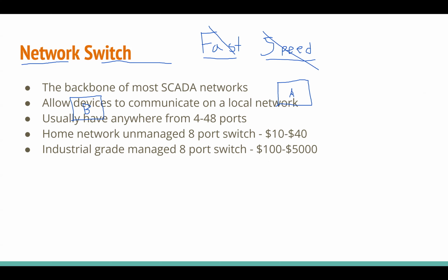It's reliability mostly. That's the really big one. I've already mentioned that we want to use SCADA now to replace some of these hardwired signals that have needed really robust reliability. We can't do that if we don't have reliable equipment. And so that is absolutely one of the reasons they're charging crazy amounts of money, even for something that does the exact same functionality: the reliability.